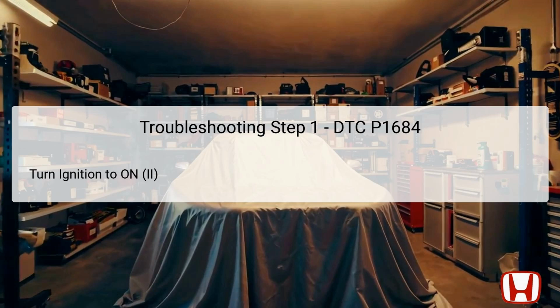Proper procedure dictates that technicians should record any freeze data and onboard snapshots at this point, as these pieces of information can provide critical insights into the vehicle's performance at the time the code triggered. This initial step sets the groundwork for the troubleshooting process, ensuring that the subsequent steps can be performed safely and effectively.